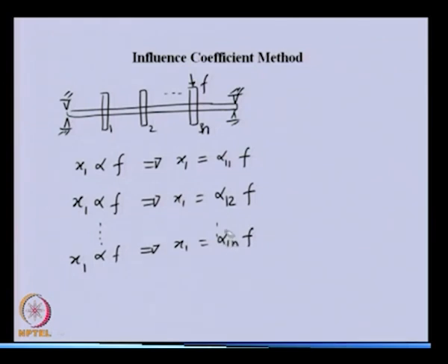Now, you can see that there is another constant, because the location of the force is different now and displacement is different now. And if we have a system in which, let us say, we are applying F1 force here, F2 force here and Fn force here, so we have n number of forces applied on all of the discs. Now, if you want displacement at disc 1, we can expect that there will be a summation of this, only we will be replacing these F's with different forces.